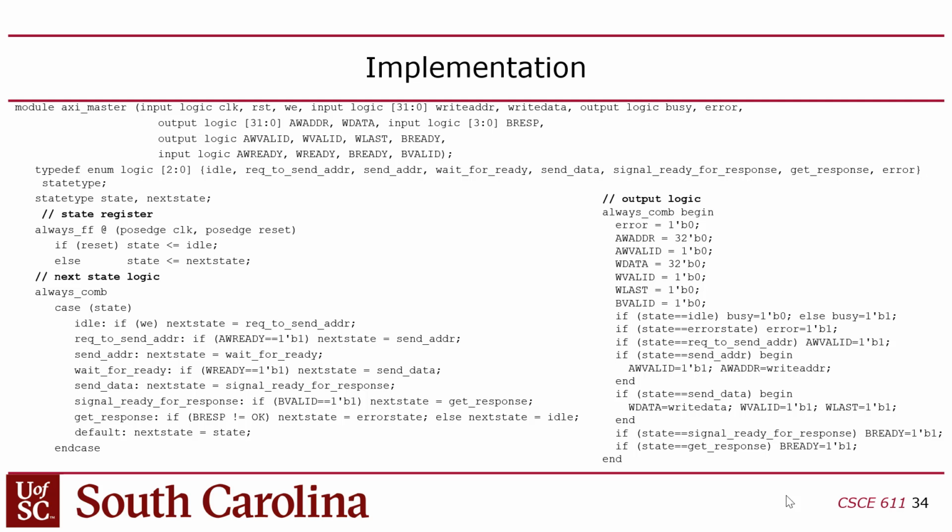And in this case, I used a state case statement there for the next state logic, and the output logic is there. So, typically you have to start with the state diagram and then transliterate that into Verilog, right? You probably wouldn't start with Verilog. You'd have to create that state diagram first. I think it'd be tough to just go straight into coding, right? Unless maybe if you're really good, you could do that. You could visualize it, right? Okay, any questions? Okay, good.